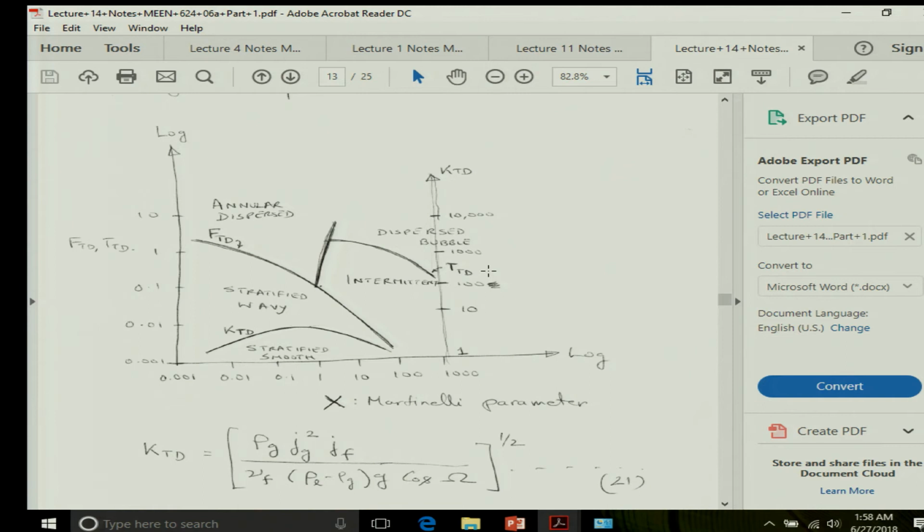Okay. So, that is as far as the flow boiling maps are concerned, and as you can see this Martinelli parameter becomes a very important factor here. Okay. So, again if you have different diameter pipes or tubes, you got to come up with your own flow boiling maps.